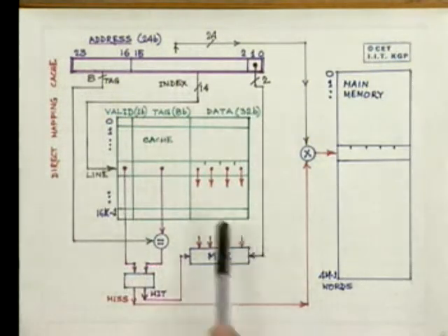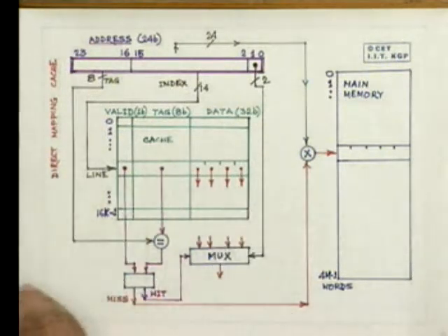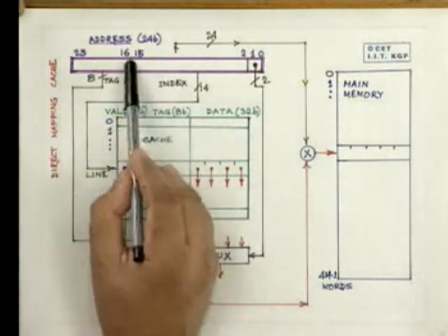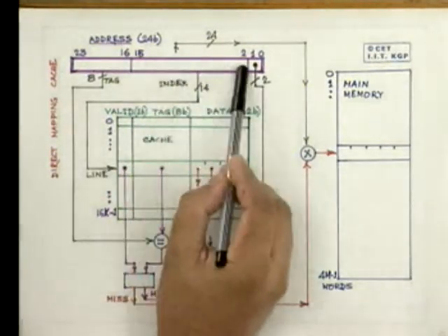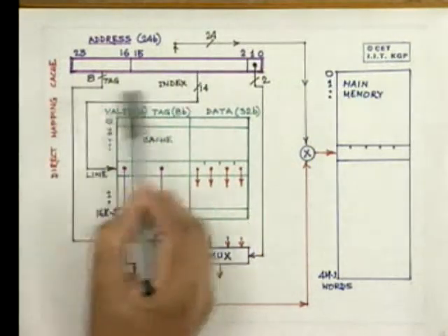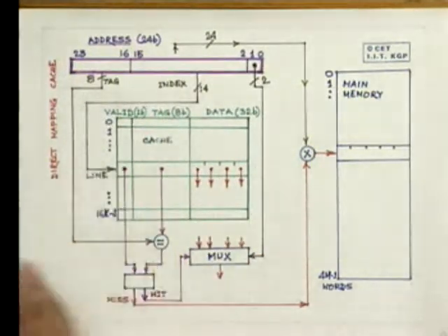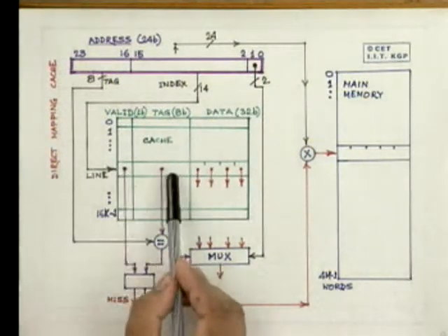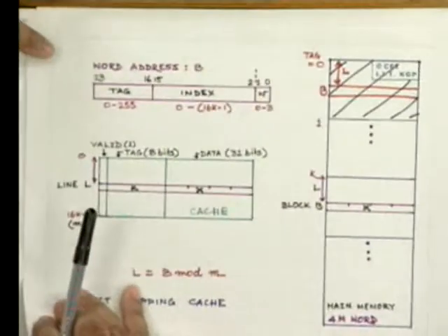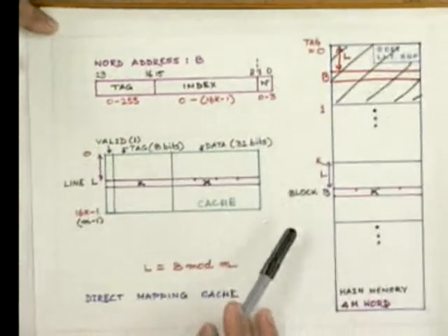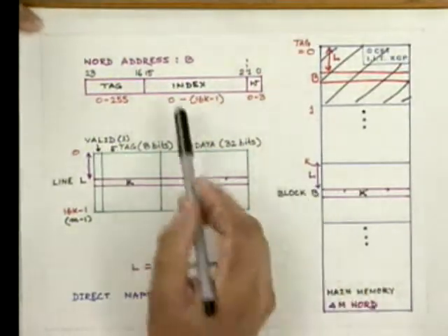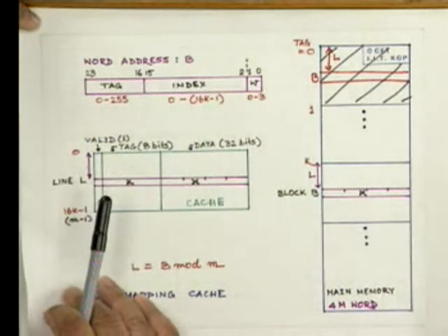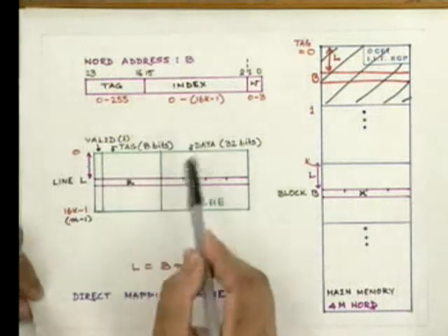What happens is that when the address is obtained by the CPU, the CPU takes this 14-bit as the address in the cache memory, and it comes into that cache memory. When it comes to the cache memory, then it has to see whether the tag bit is matching with that address's tag bit or not, to know which particular block's content is here.